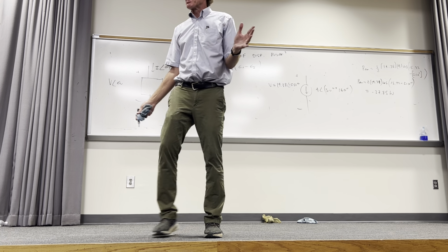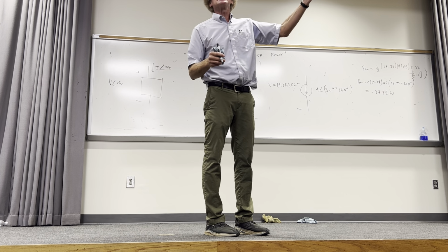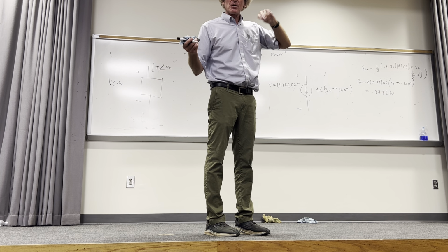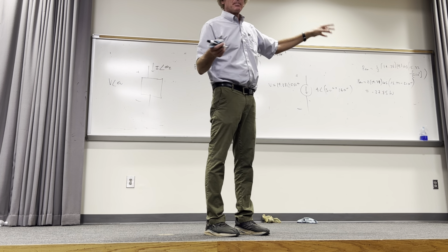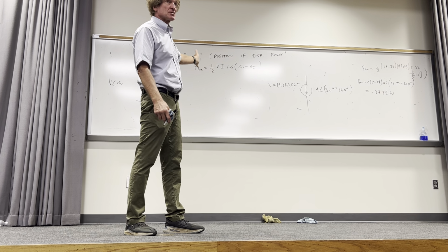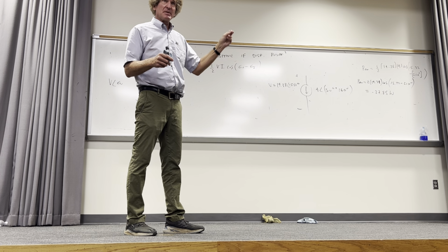I'm a little behind here, but for that problem, there are obviously many steps to it. The key is getting the voltage, the way I did it. From the voltage, you get the currents. From the currents, you get the power dissipated by the resistors. Can everybody see you can get the actual power associated with the voltage source too, just by getting the current? You all follow me, class? And then you can do that. That's how he did the problem. There are many steps to that.